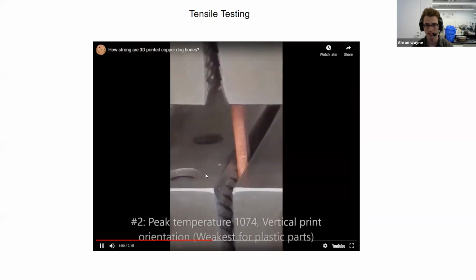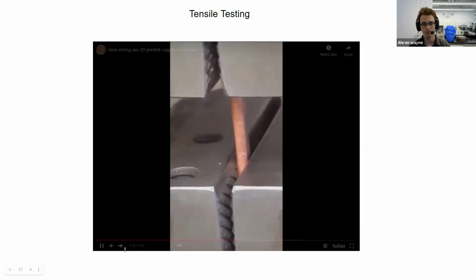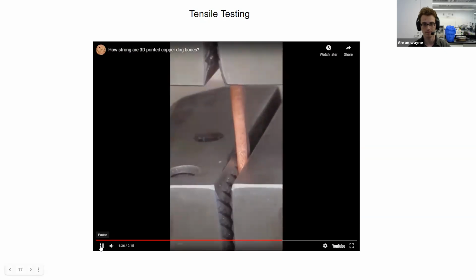And then this is printed at a higher temperature. 700 newtons, 800, 900, 1,000, 3 millimeter extension, 1,100. This is where it broke before. 1,150, 1,200, 4 millimeters, 1,300. And we get some very good extension and a very nice necking that occurs.